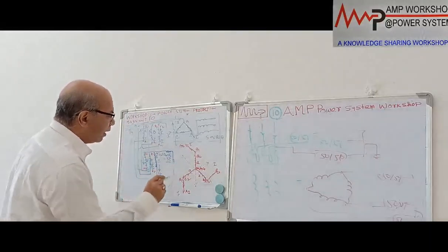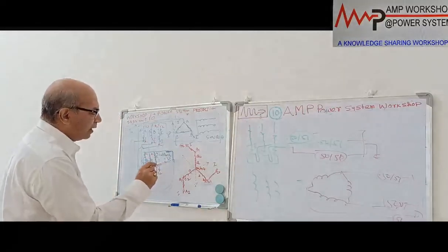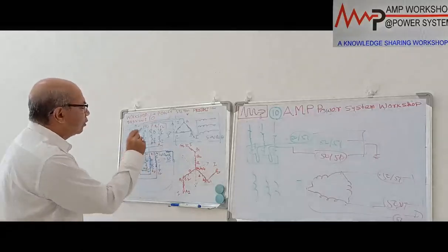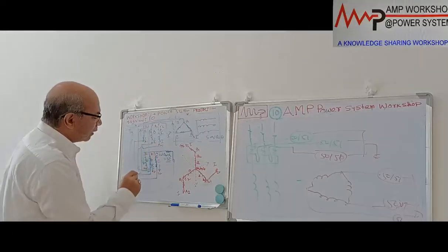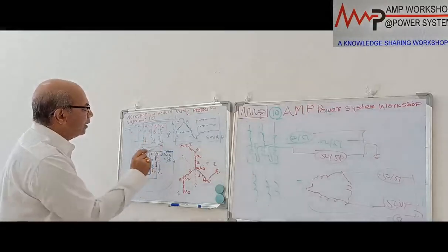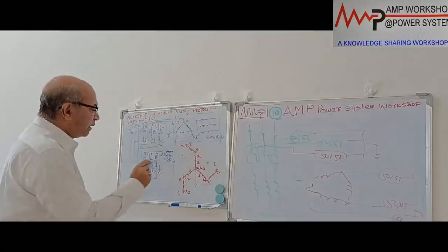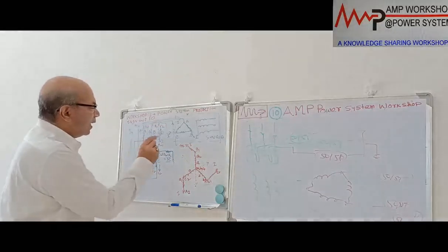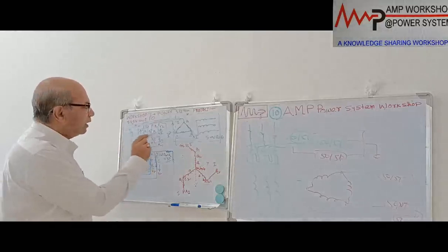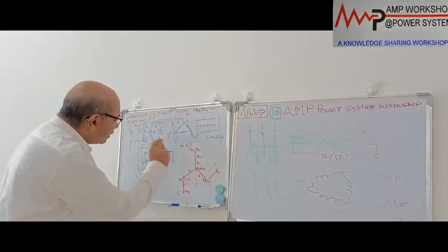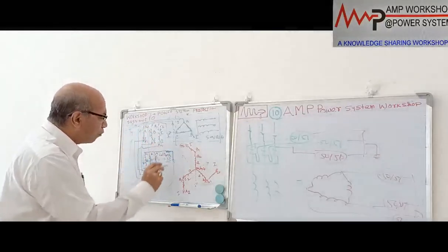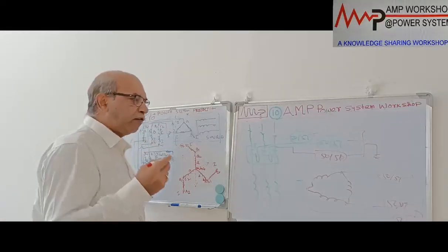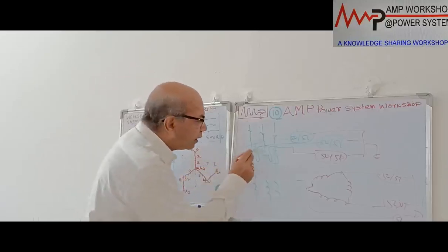Arc fault current will come over here with the neutral carrying 3 times the current, 3I, flowing through here. It will be distributed as I in each phase. So the current flowing through the transformer is I in each phase, but this is a 0 sequence current. All the currents are identical. There is no unsymmetrical value of current. All 3 currents are identical, so it is a 0 sequence current. When 0 sequence current flows through a transformer winding, there will be a 0 sequence current flowing in the secondary side of this CT.